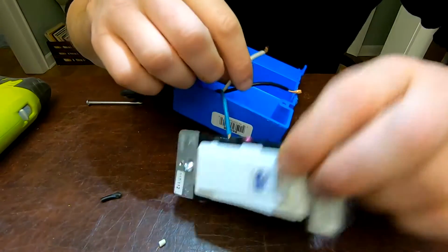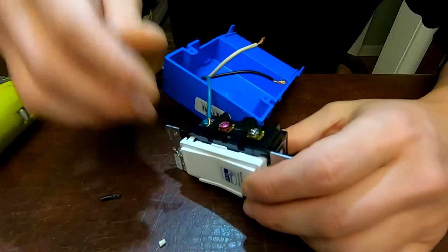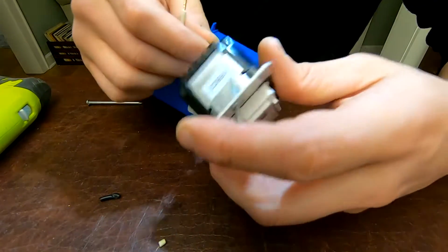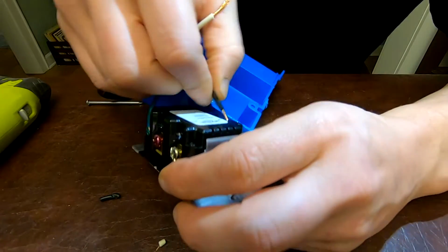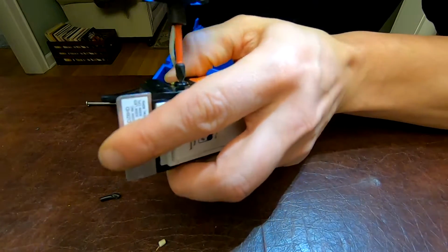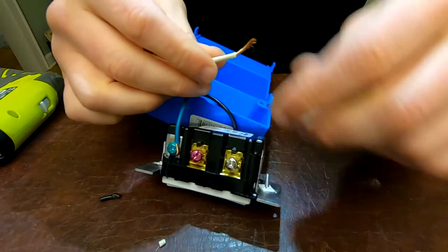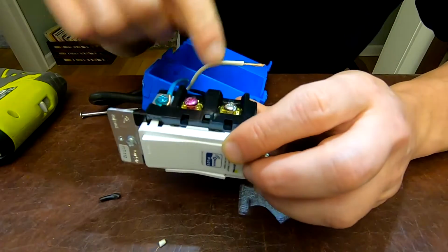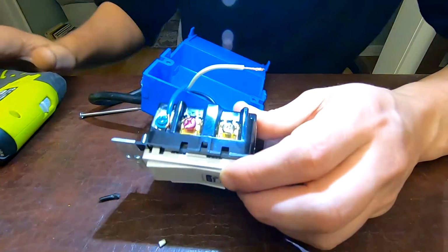That's super secure. Now once again, this one's only for 3-way switches. Leave that label off if you're using this model. White, black. So black we can go ahead and tighten to where it belongs. Good, nice and secure. White, we're going to hold off on tightening down, because remember, we have to jump the neutral back out of here to our other single gang, which is going to be where the transformer plugs in.